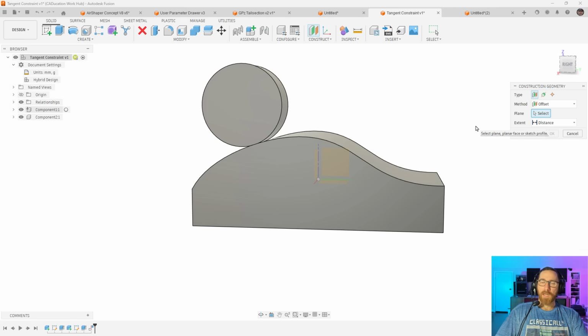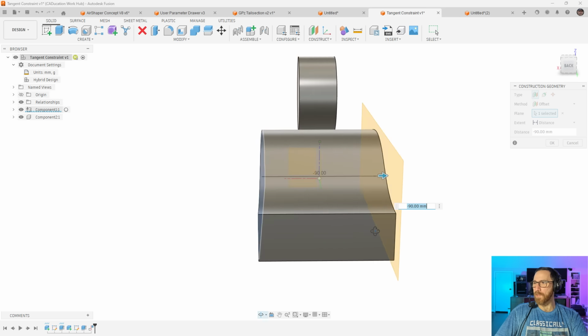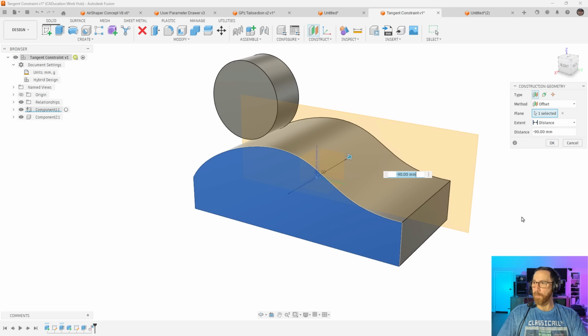So in other CAD packages, a lot of times you'll go in and you'll click create construction plane, and then based on your selections, you will get the available options for the type of construction plane to get. That is not how this works. This is essentially just a picker that lets you select the type and then go through a drop-down list for the things you want. There's no inherent logic in your selection, for example. So, if I select these two faces, it's not going to give me a midpoint plane. It's still looking at whatever you have in your dropdown.